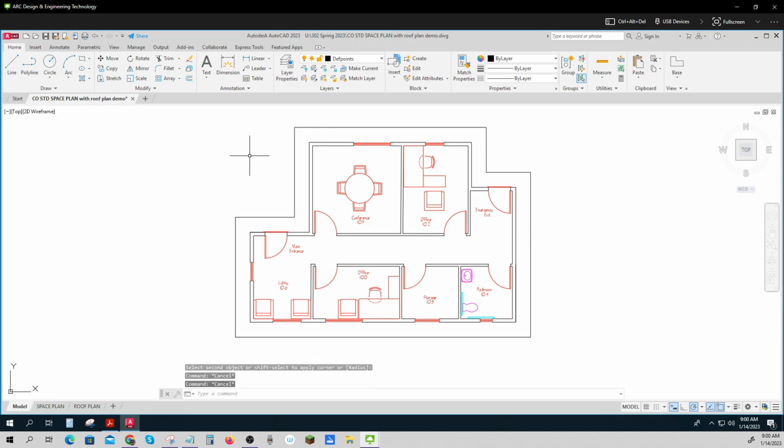Now, when you draw a roof plan, the idea is that all the angles off of a corner are 45 degrees. That's just what a plan view looks like when your roof slopes are all the same. So let me set my tracking for 45 degrees, and I'll just start. Oh, and I did that. Those are on the walls.